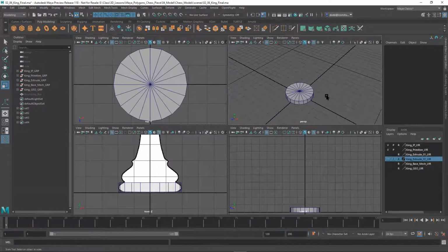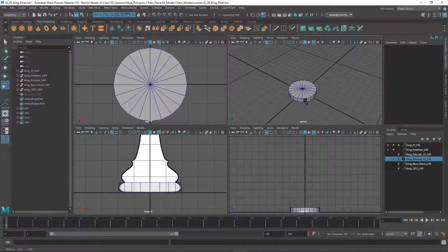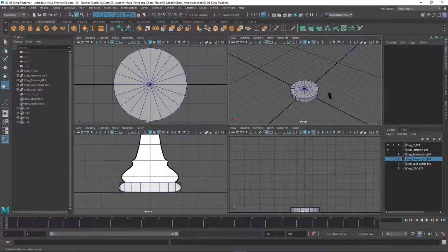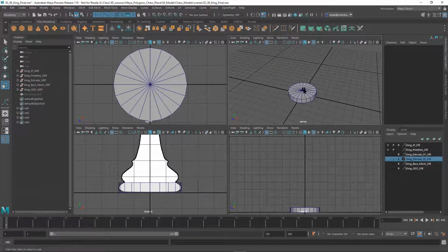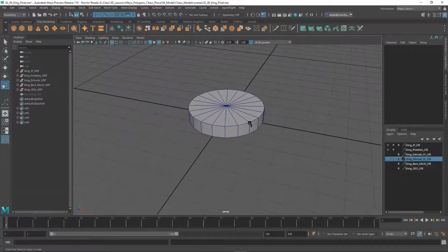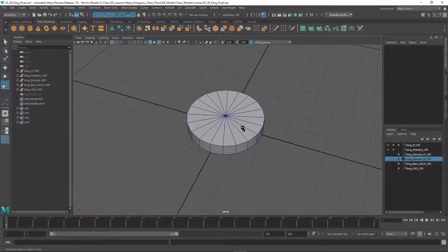All right, now here's something interesting. I want to keep it closed on the bottom here, but I don't need these here, and they're going to make it a little tricky for the faces on the top. The faces on the top are going to make it tricky because I really want to be just extruding these nice quad forms, and I've gone over why you don't want to really be using triangles as much as possible for printing and for modifying purposes. There's a whole variety of reasons. So what I need to do is I need to delete all the faces on this top here.